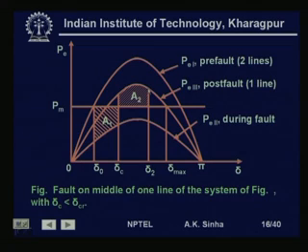So, we have deceleration. Of course, rotor angle will keep on increasing till the speed, because of deceleration, reaches back to the synchronous speed, which happens say at this point delta 2. So, we will get the decelerating area, which will be between this Pm and under the post fault curve here, A2. So, when these two are equal, we will get the final operating point here, that is delta will start from here, jump here, move like this, go up to here, and then it will keep on oscillating about this point.